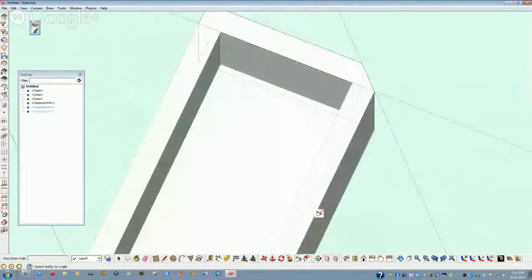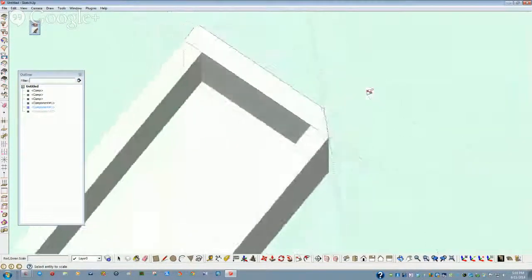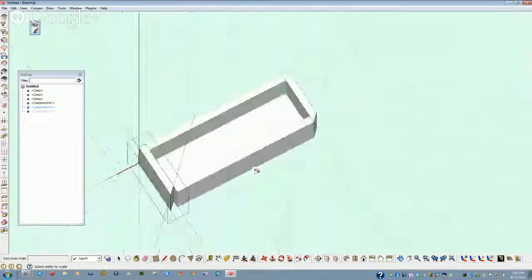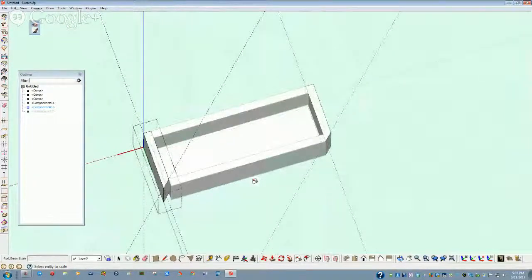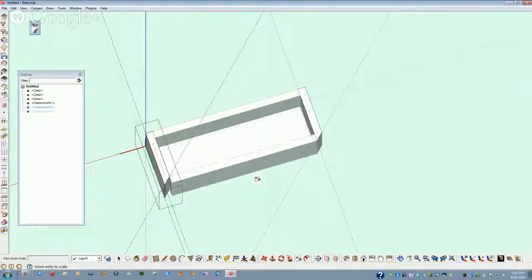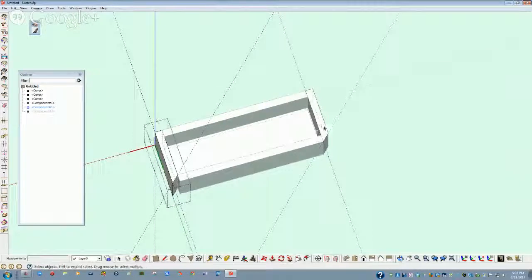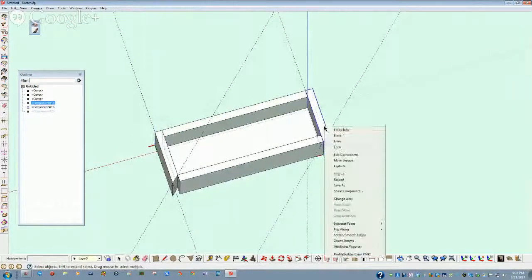We also have a miter on this corner, the wrong direction. So this is something you have to keep in mind when you are making just copies of elements. Sometimes you would rather copy them in a circular format than in a linear format, which I could have done. And I will even go do that by hiding this one.